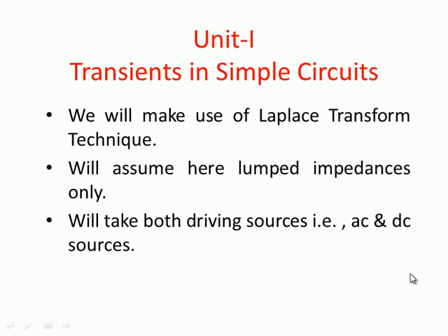And the second case, we will assume here lumped impedances only, as I already talked about in last semester about lumped parameters, lumped impedances. Actually, if you see the resistance or inductance, it is uniformly distributed along the line, but whenever we do calculations, we always use lumped parameters so as to make our calculations easy and simple. And later we will take both the circuits, AC and DC sources, driving R, L, RLC circuits. So let us start with the first one,